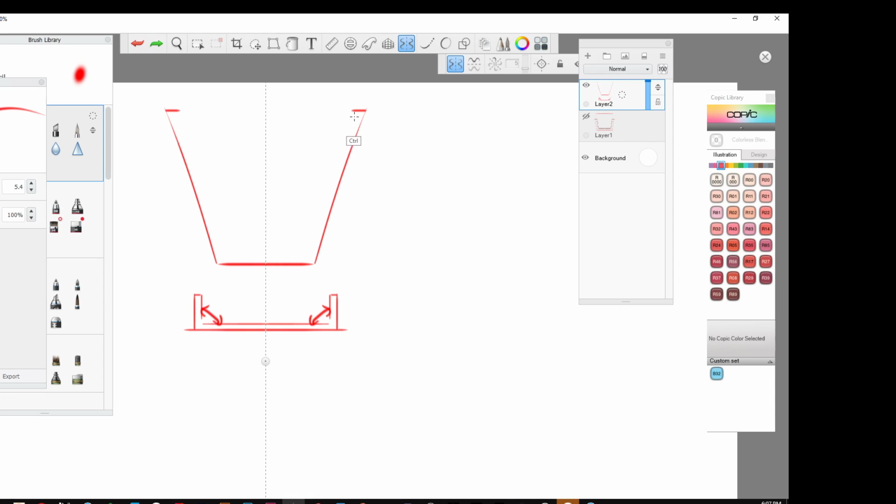Now, that can really affect the design or the style of what your product looks like. So even when you're doing concept sketches or the initial 3D models, you always want to have an understanding of what your draft is. There is nothing more that I hate than industrial designers who do all these sketches and should know better, 10 years into their job, 5 years, and they show these models, they show these renderings as final designs, and they don't take any draft into consideration.